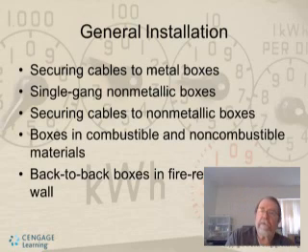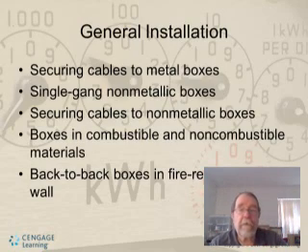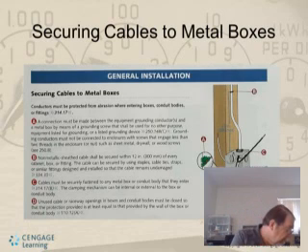Now, general installation, you're going to get securing cables to metal boxes, securing single gang non-metallic boxes, securing cables to non-metallic boxes, boxes in combustible and non-combustible materials, and back-to-back boxes in fire-resistant rated walls. We're going to talk about some of that here. The next slide is going to talk about general installation, which is what we're talking about.